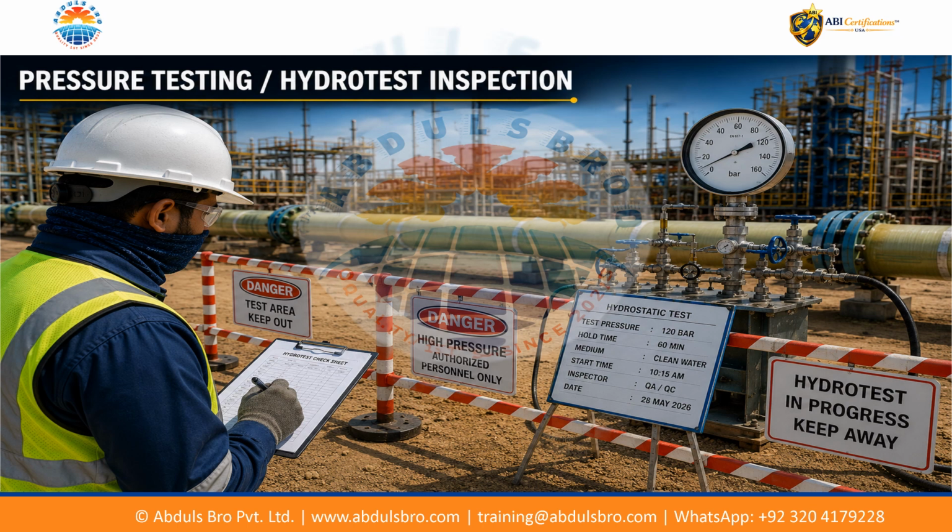During the test, pressure is maintained for the specified duration while accessible joints are examined for leakage. Any defect requires appropriate corrective action and retesting before acceptance, depressurization, and system reinstatement.